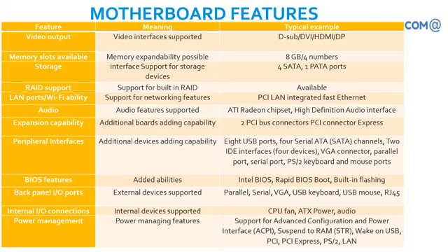Memory slots, yes. Storage, normally we will have IDE ports, that is PATA ports, and SATA ports, serial ATA. Minimum they are providing four, so maximum four disks we can connect. RAID support normally is not available for normal desktop motherboards.